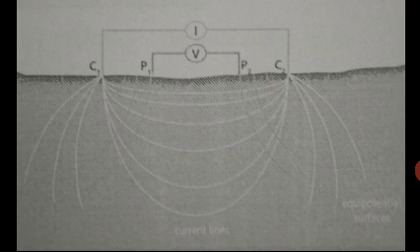There are two variations of the resistivity method. One is the profiling method, that is lateral exploration. Second is the sounding method, that is the vertical electrical sounding, VES. Electrical profiling or traversing is done to detect lateral changes in resistivity, which reflects the surface lithology in a large area up to the same depth.